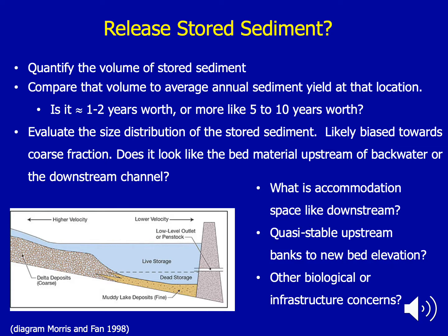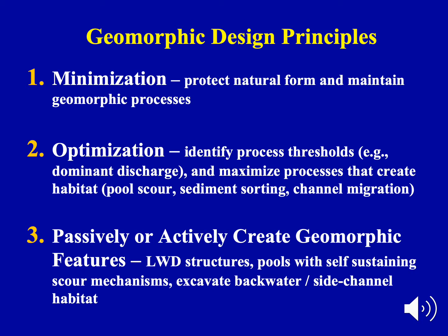In a culvert, because they're really inefficient traps, all this fine stuff tends to flush right through. So usually your sediment upstream of a culvert is biased towards the coarser fraction, often the stuff we like from a biological perspective, coarser sediment. It also can mean it's harder to transport if you're in that depositional zone, since it is biased towards the coarse fraction.